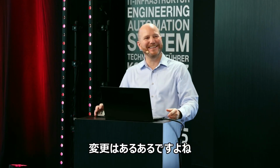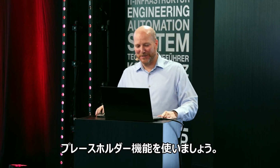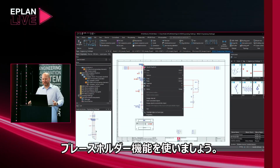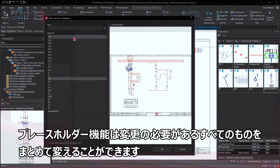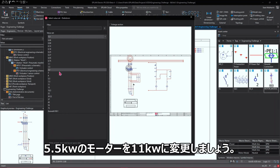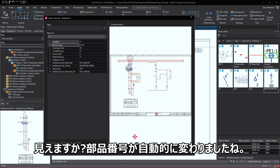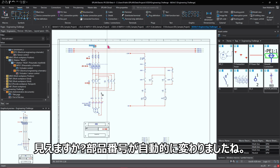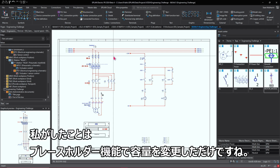Oh, exactly. Come on. So, well, it's not a problem in Eplan either, because you simply select this placeholder technology, and this placeholder technology carries all of those values that you need to switch. So by simply going from a 5.5 kilowatt, what did you say, 11? 11? Yeah. So let's select an 11 kilowatt motor. You can see that the part numbers automatically get adjusted, and I really don't have a lot of work to do. It adapted all of my protection devices. It adapted my cross sections, and everything's done. So that was really not a lot of work.